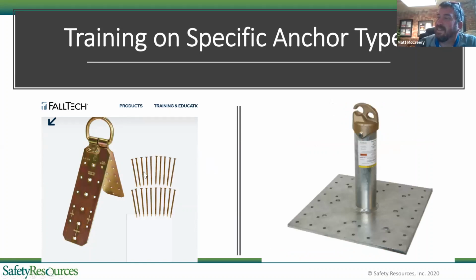So there's your 16D nails. That's for your sheeting. I see on a lot of flat roofs, you see your permanent fall protection systems, but we don't see that very often on steep slope. However, I have seen truss manufacturers install anchor points at the peak, and those have been pretty awesome to use because then you can just flash them in and bend them over. But again, that's a residential application, and I don't think we have too many of y'all out there in the MRCA.